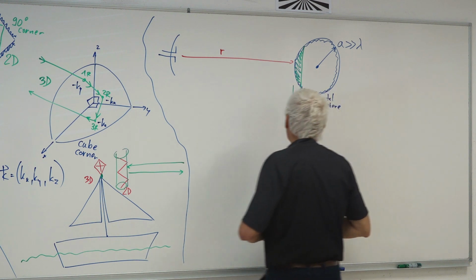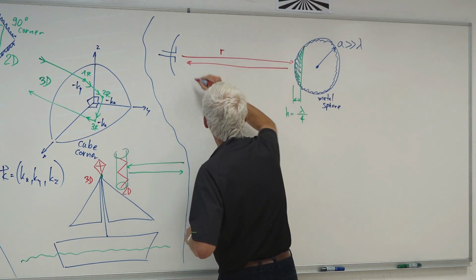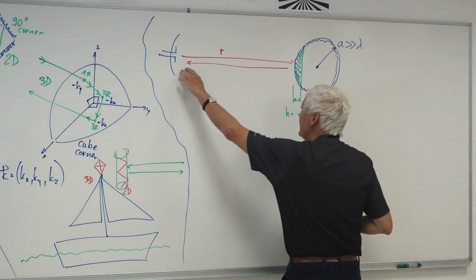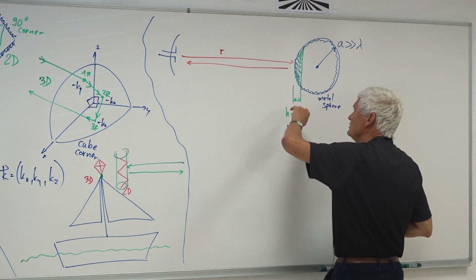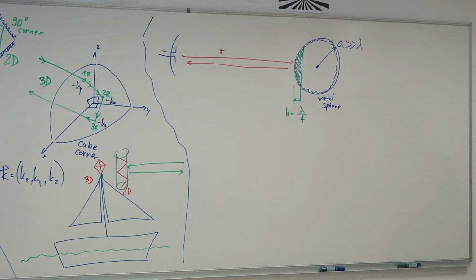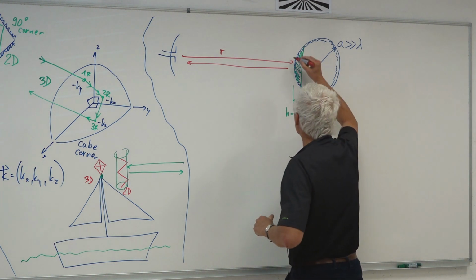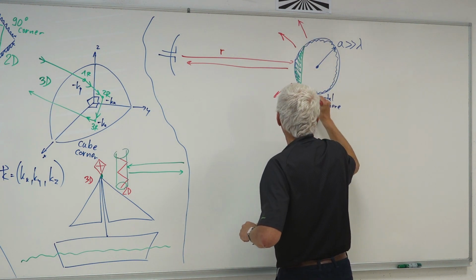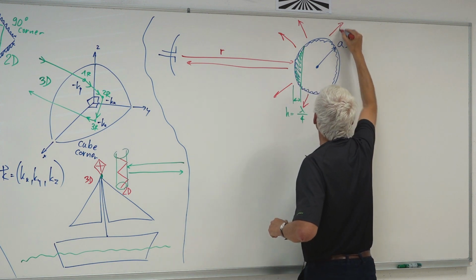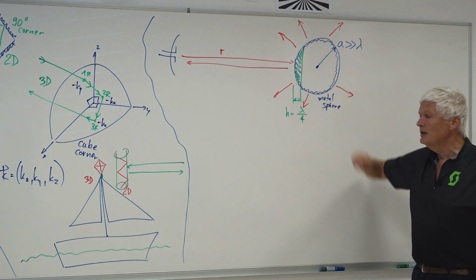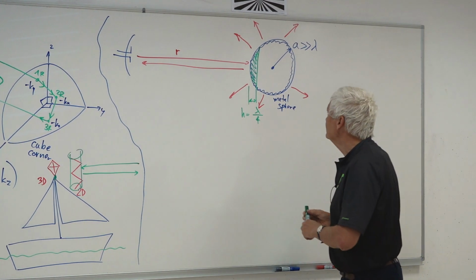So for the reflected wave, this is already a phase flip of 180 degrees. There is very little flip because of the changing distance from the radar, but a very big flip because of the curvature of the ball. So what is now the cross section of this metal sphere? Of course, because it's round, it scatters radiation in all possible directions. But for a monostatic radar, it's sufficient to know what comes from this first Fresnel zone.